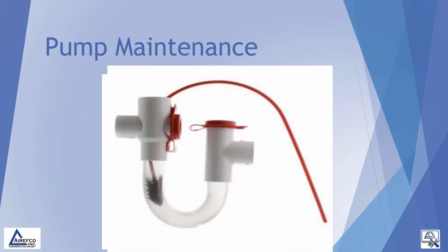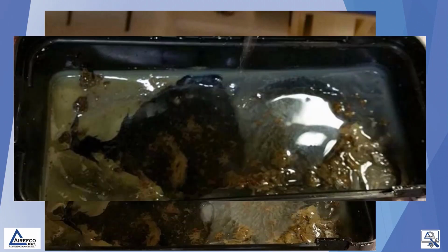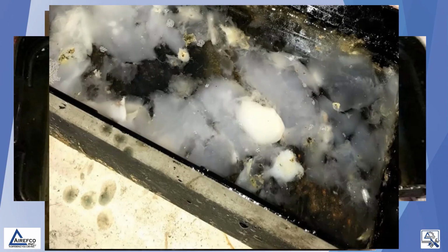If you have a condensate trap like this on your air conditioner or furnace system, you'll see this garbage and debris that builds up in these traps. This is why this particular model is sold with a brush so that you can run it through and clean out the trap. The same thing needs to be done to the condensate pump. So over a period of time of running, a condensate pump is going to build up various debris and gunk in the bottom of the tank. And so it's very important as part of your maintenance that you would open it up and clean out the tank and make sure that it's not corroded up like this.